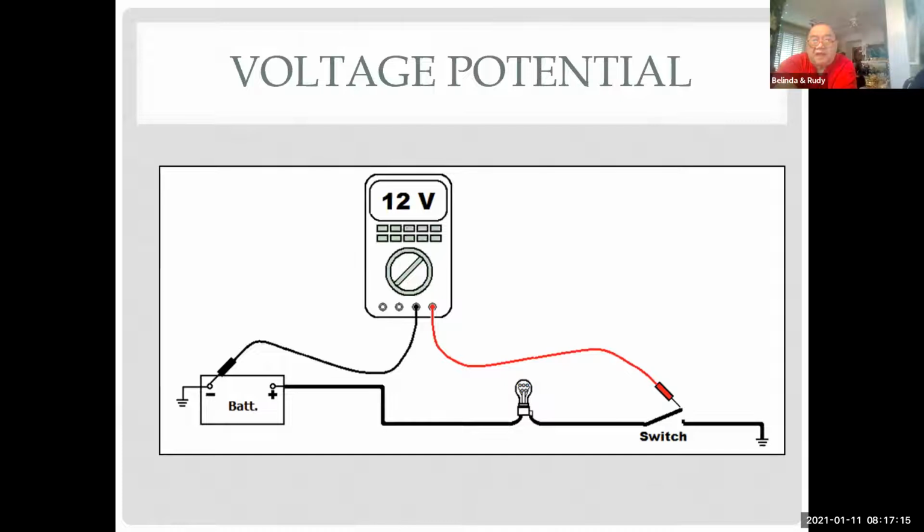So when the switch is closed and the current goes to the bulb and goes to the ground, you mean to say the voltage passing the switch, which is closed, is 0? Well, if I close this, then the bulb is going to use all my voltage. So it's going to use all the 12 volts. So I would have 0 volts left after the bulb once I close. That's what I want to know. Exactly. Also maybe the bulb might only consume 6 volts. Right, so there's another 6 volts coming out.